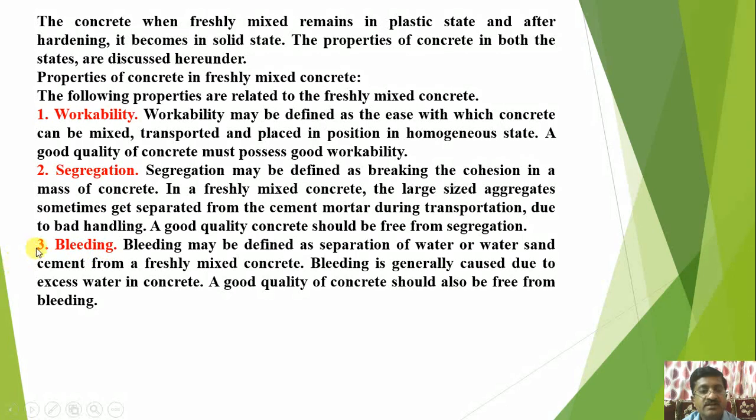Third is bleeding. Bleeding may be defined as a separation of water, or water, sand, cement from a freshly mixed concrete. Bleeding is generally caused due to excess water in the concrete. A good quality of concrete should also be free from bleeding.